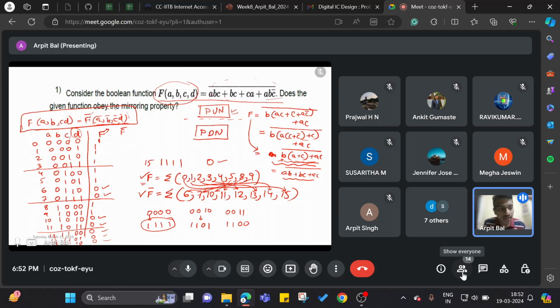The only thing is the inputs will be taken in complemented form in the PMOS stack. The benefit is, let's say the number of stacking in NMOS is less than in PMOS, then we can copy the NMOS stack on the pull up network as well, so that the stacking gets reduced.